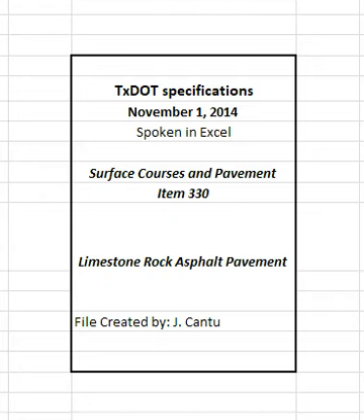Use only water or an approved release agent on rollers, tamps, and other compaction equipment unless otherwise directed. Keep diesel, gasoline, oil, grease, and other foreign matter off the mixture.